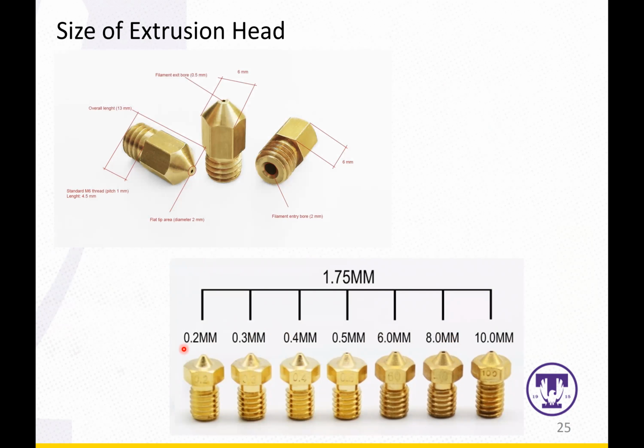most of those FDM manufacturers keep it as a secret, because these rules only work for their machine, because the size of this nozzle works together with other factors, which will affect the surface quality of the printing.